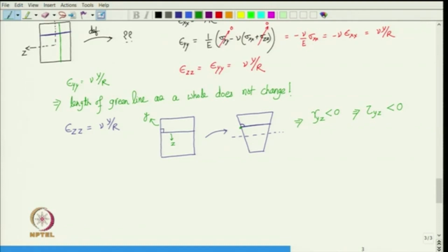Now, see what surface is that? So, this surface is actually Z surface, is not it? So, the beam goes into the paper and the surface is then the Z surface, its normal is E z or E 3 and it is a free surface, is not it. When we are bending the beam, we are only applying moment on the end cross sections which were the x plane, but the lateral surfaces were free.